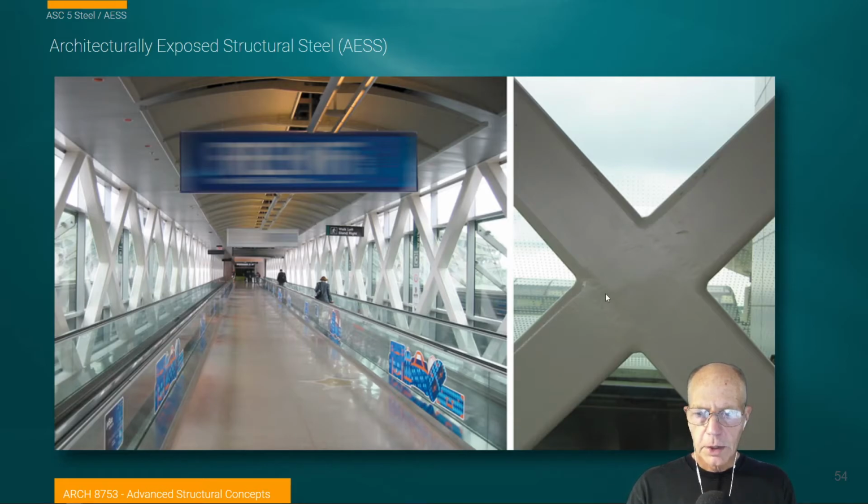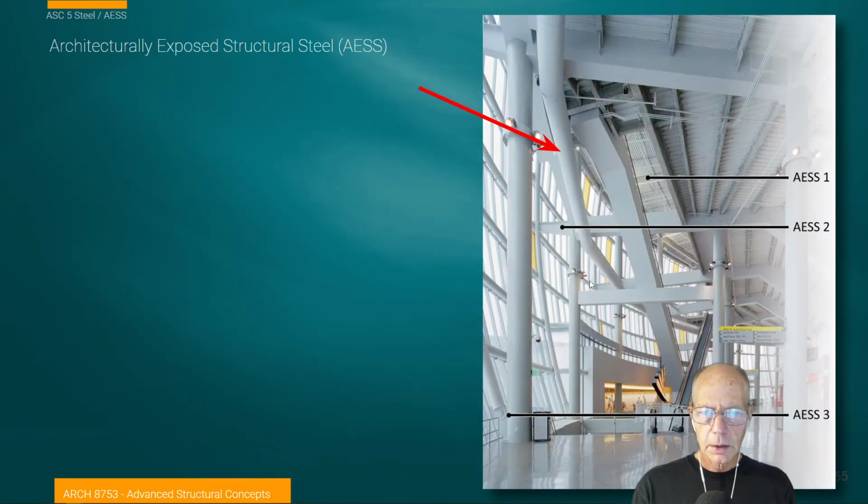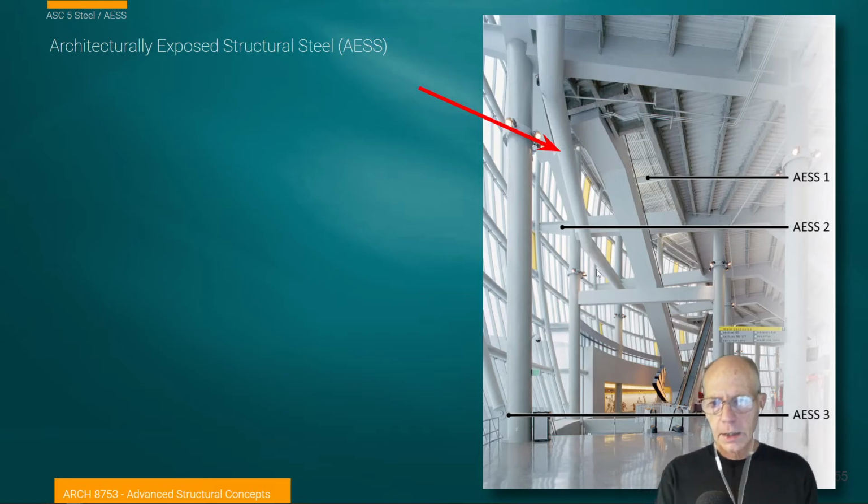I think that could be considered to be perfectly acceptable. This is a really heavy steel kind of structure, fine and passable. And actually, you would commend the fabricator for doing such good quality work with that fabrication. But it still may be a surprise to you that kind of detail shows through when you expected them to look completely clean to each other. And that gets on to another idea. There is a chart I'll show you next about this idea about how close you are to something and then what level of quality it has.